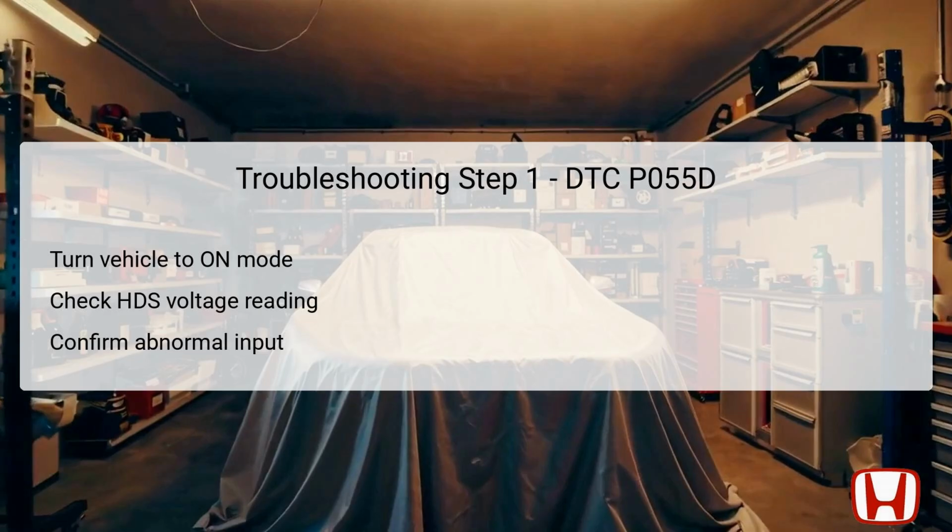If this value is found to be greater than 4.79 volts, it confirms that the failure has duplicated, indicating the necessity for further inspection. This step is crucial as it establishes a baseline condition from which the technician can determine whether the sensor is malfunctioning or if another issue exists within the circuit. Observe any stored DTCs as they could provide additional insight.